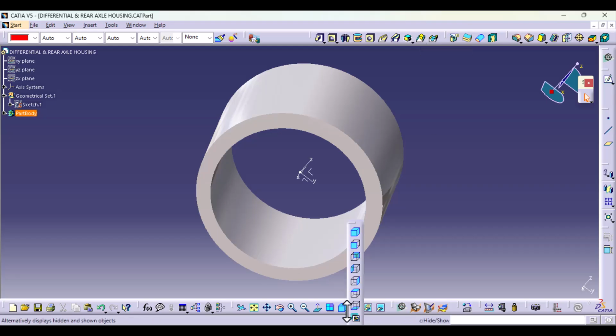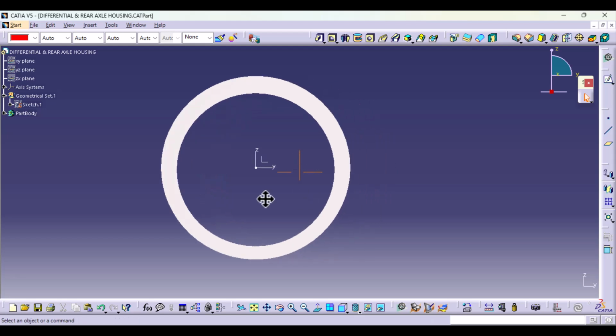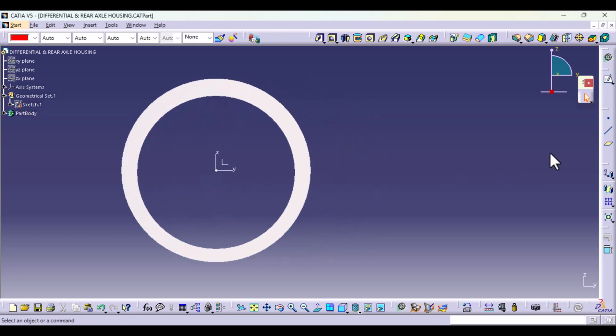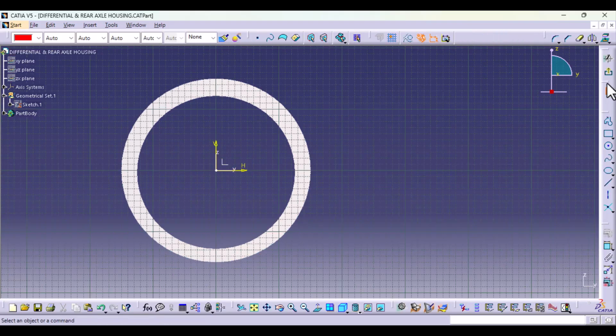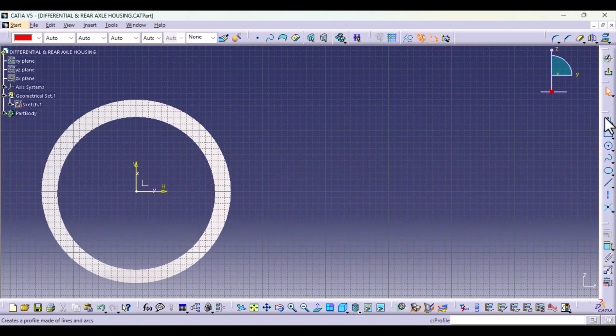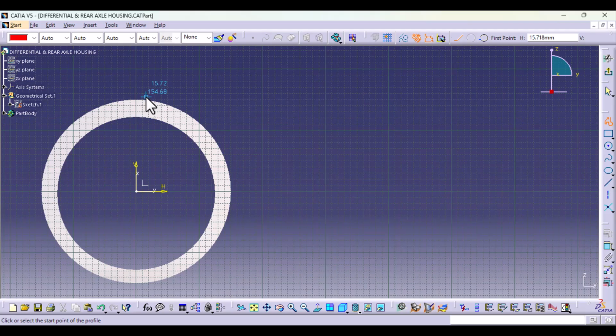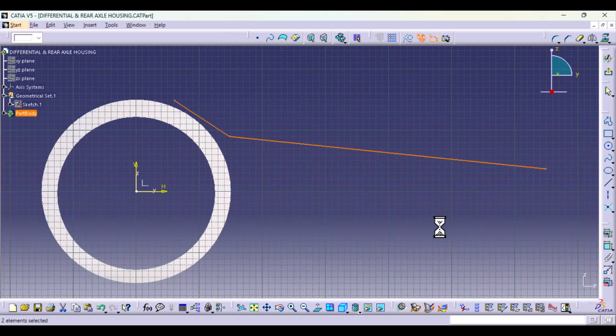Okay, I'm going to use this as our reference. Let me go to the front view. So this section here, which will be our upper side, you can sketch the ZY axis and select profile, create a basic profile. Perhaps I can start here first. Create a basic sketch like that, add some dimensions.